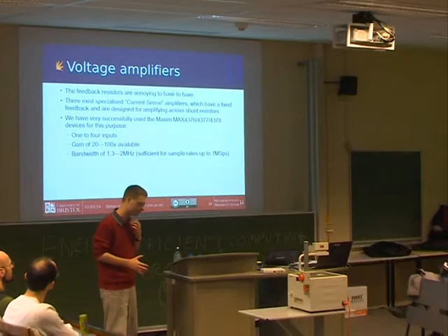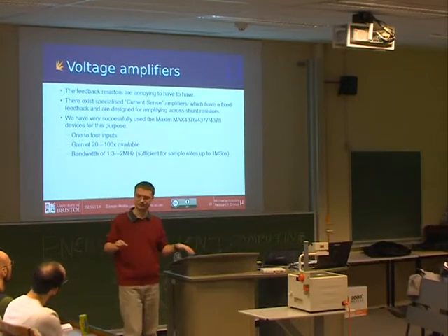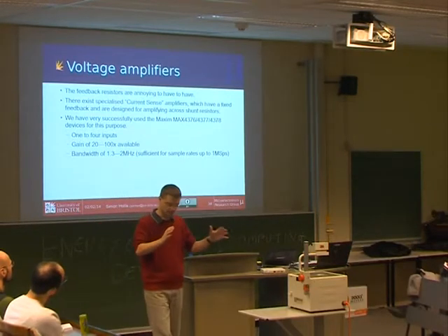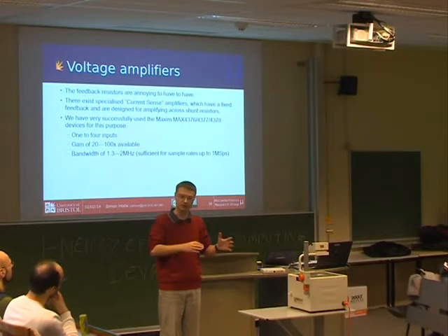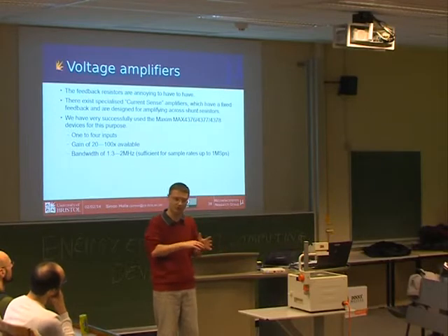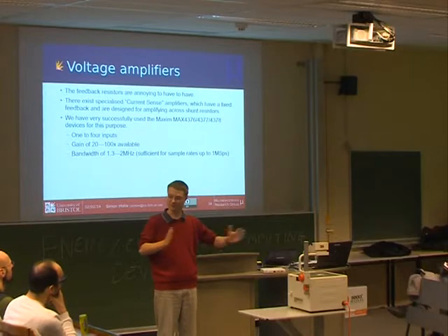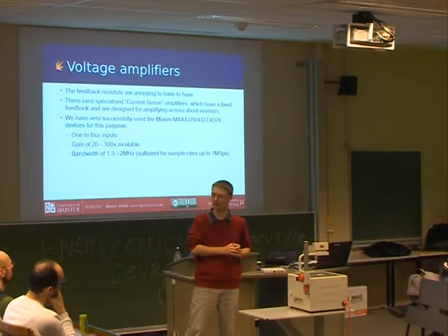One of the things that happens when you pass through a filter is it fundamentally smooths the signal. If you were to take an infinite number of samples of the output, you'll get the same representation of the total energy. But what you don't know is the shape of the curve. You don't know when it went up and when it went down, but you will see the total used. So you lose the ability to say it was that part of the loop that took a lot of power.